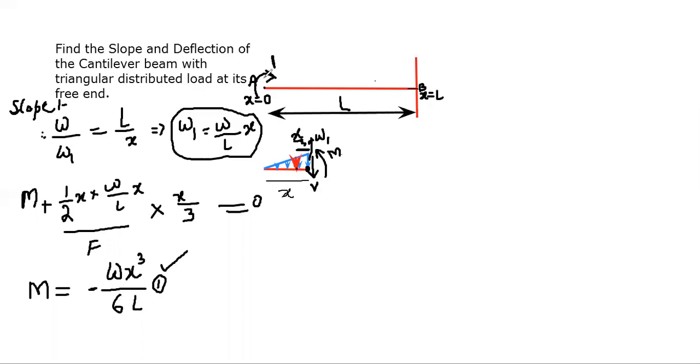Once you have removed all the loads from the beam, we have to find the slope of the beam at point A. What we are doing is removing all the loads, and at the point where we have to find the slope, we are assuming a moment of 1 unit, clockwise or anti-clockwise. This is your choice. Let's assume the moment is applied clockwise, and its magnitude is equal to 1 unit. Once you have done this, now do the analysis again.